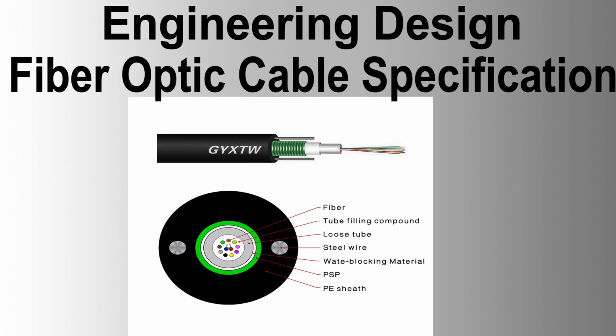Civil Works. HDPE Cable Conduit Routing Plan. Pre-construction survey. The contractor shall perform a pre-construction survey along the planned cable conduit route to identify and accurately locate all existing third-party facilities above and below ground to the satisfaction of the company.